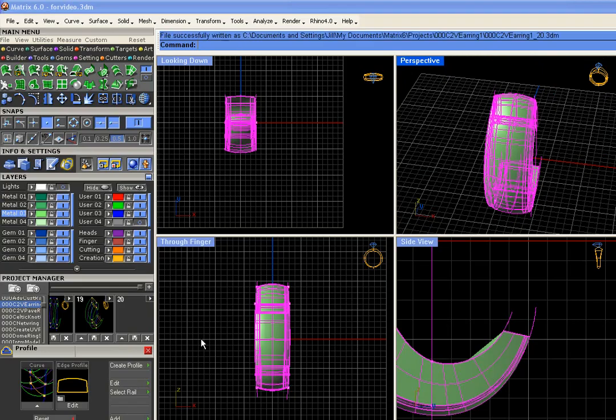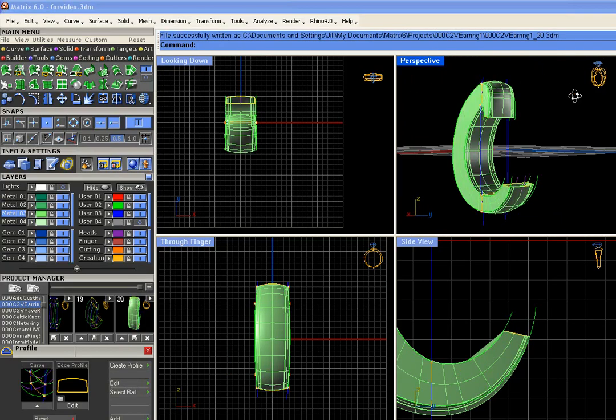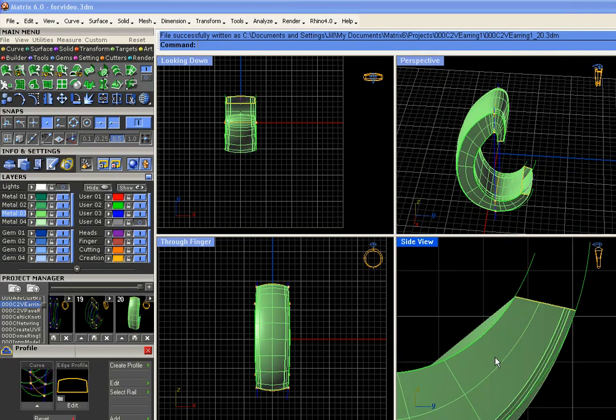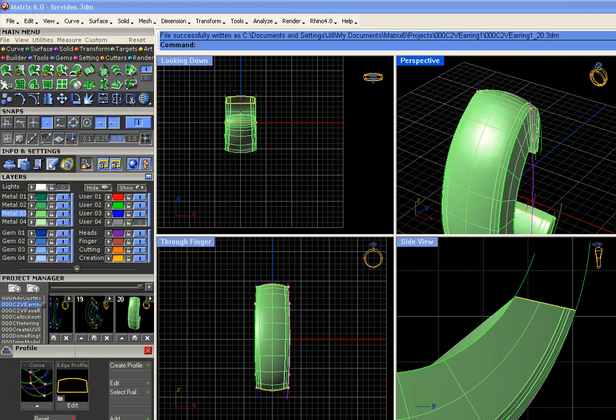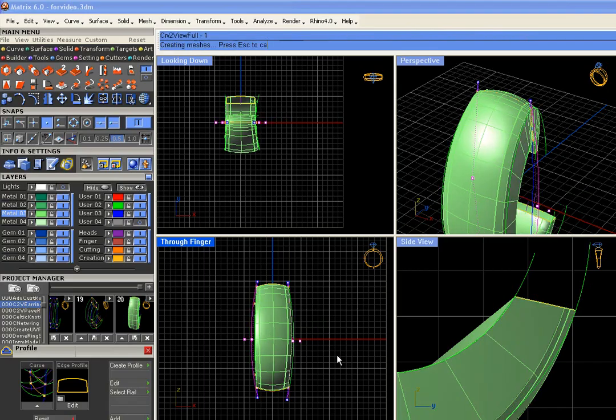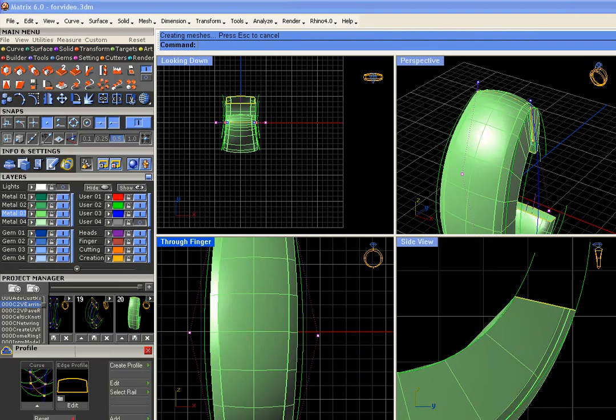So just remember what the history can do. We can change the profile shape and size and location. Okay. We can even take the original two curves now, turn on their control points, select them, run the transform command, and from F4 we can scale this up or down.